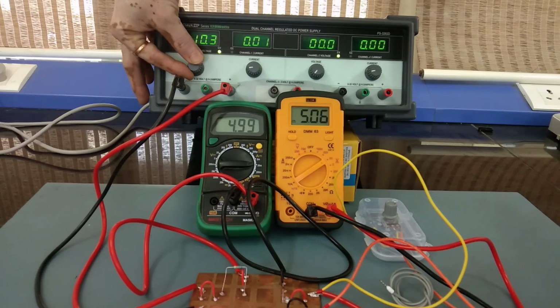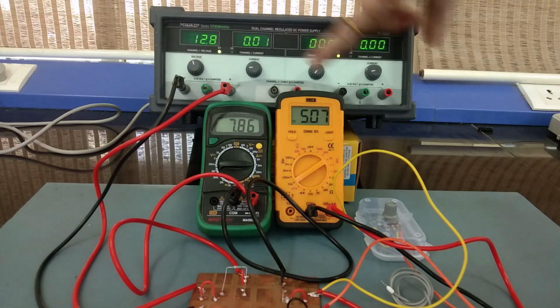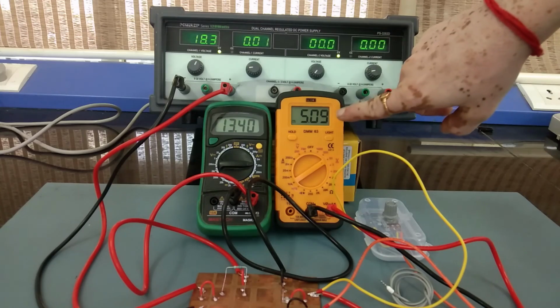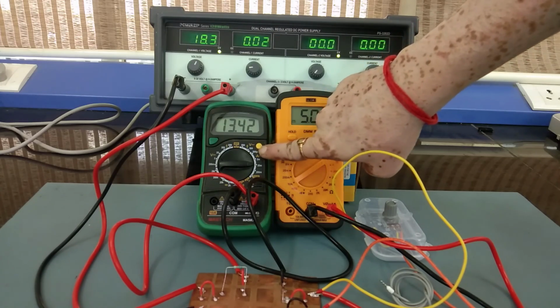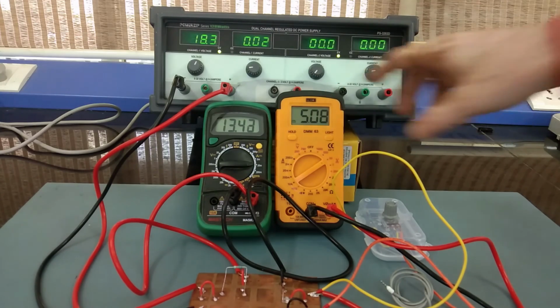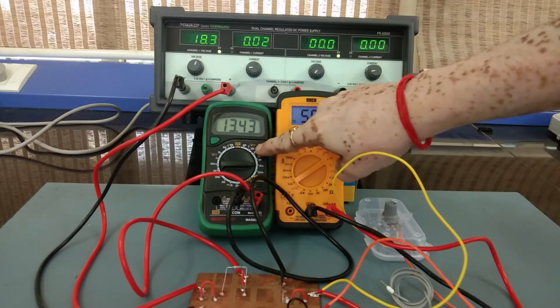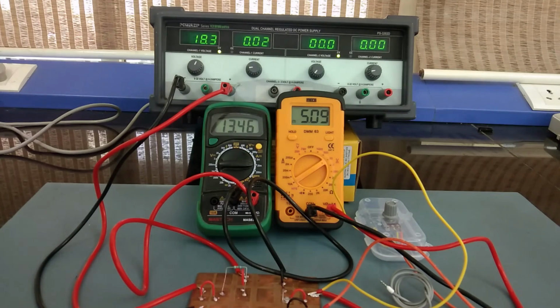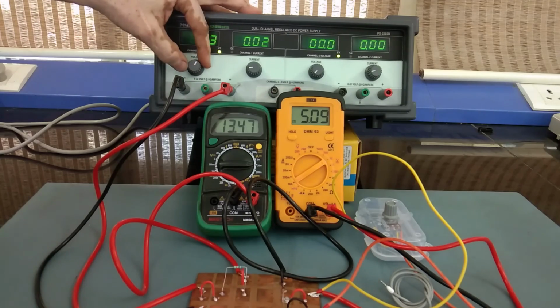Alright, again you can see I have kept the load at certain value and I will change the line voltage. You can see the current changes. However, the voltage is keeping constant. I will go a bit higher maybe. I am at around 18 volt, but still you can see the current has increased, but the voltage is remaining at constant value. So this shows that the Zener is an excellent voltage regulator. So the line regulation behavior and load regulation behavior is considered.